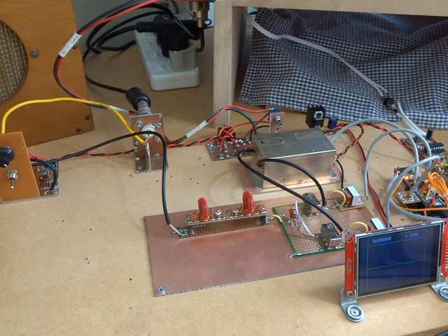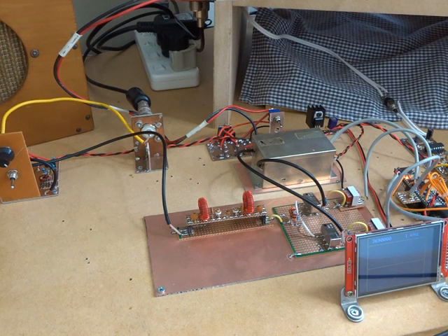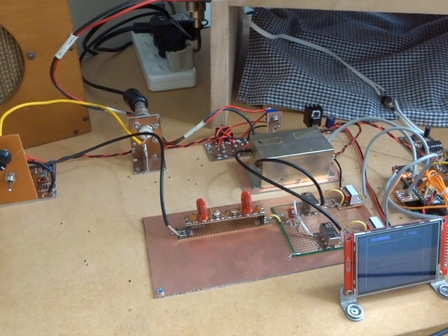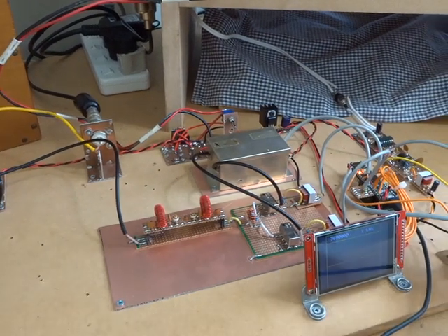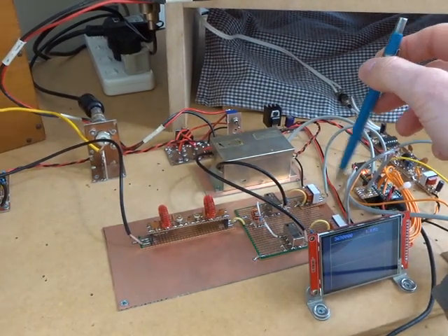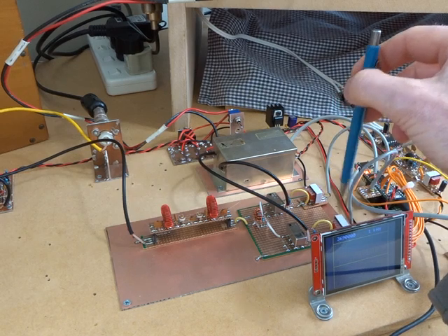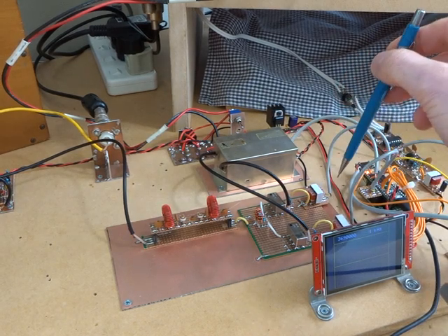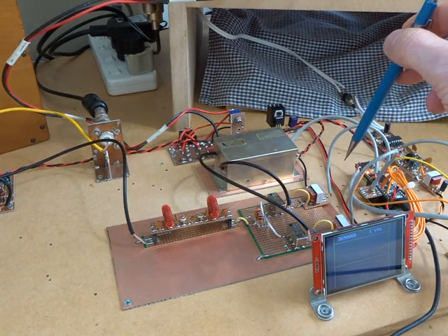Again, not optimized. I'll just cease transmission and then change to the upper sideband. So that's now on the upper sideband. There's still just a little bit coming through, and then back to lower sideband. Much better. Again, as I just said before, I haven't optimized any of the levels coming in. It's not unusual to try and vary the levels coming in to get better suppression of the unwanted sideband.